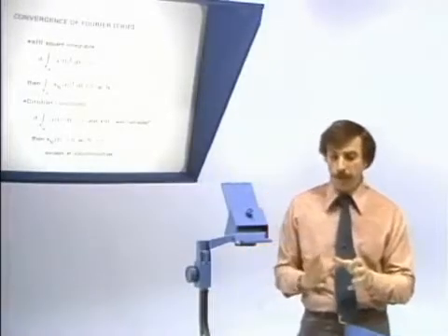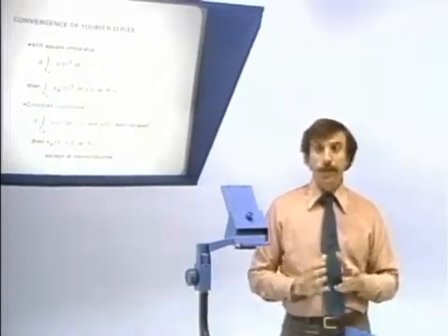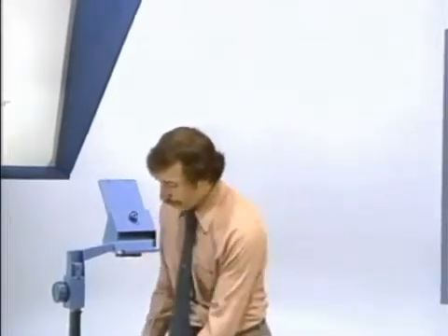And what well-behaved means in that statement is that, as discussed in the book, there are a finite number of maxima and minima in any period, and a finite number of finite discontinuities, which is essentially always the case. So under square integrability, what we have is the statement not that the partial sum goes to the right value at every point, but that the energy in the error goes to 0. Under the Dirichlet conditions, it says that, in fact, the signal goes to the right value at every time instant except at the discontinuities.